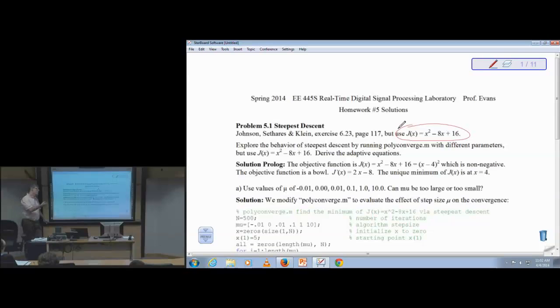So this measure that we use will be application dependent. We can go after signal to noise ratio, bit rate, closeness to an all-pass response, whatever measure we want to come up with. And then once we have the measure, we can figure out how the subsystem, the equalizer, for example, how those coefficients affect this cost function.